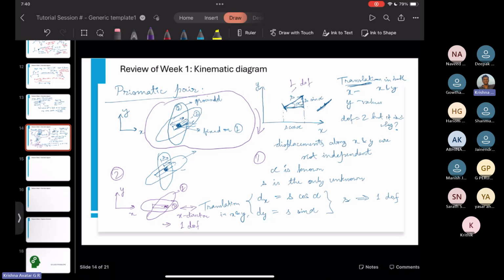And in this case, by rotating and using the other definition of mechanisms, to have a mechanism we need relative motion. But when we rotate the entire mechanism, the relative motion does not change. If it was moving with respect to this direction, say we fix this axis and this axis, making some angle theta, even now it's still making an angle theta, which means we have not interfered with the relative motion.